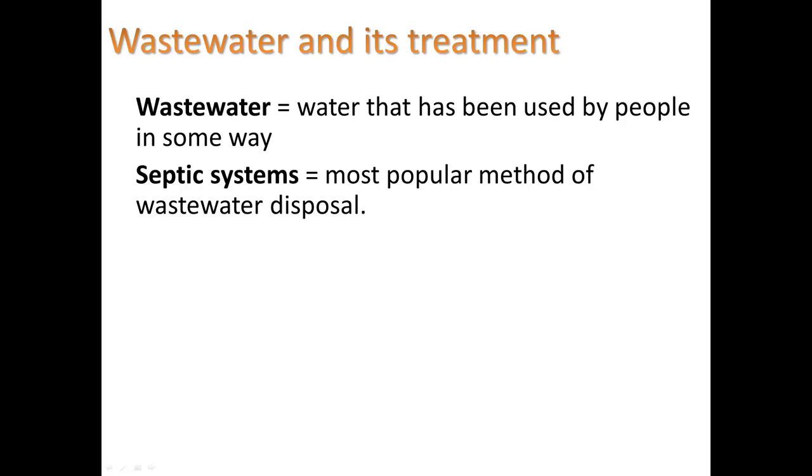Basically, the water from my drains goes into a large tank that's underground, not far from my home, maybe about 10 meters away. And it's large, like 5,000 gallons or so of volume. And the water, as it's sitting in there, is being basically purified by microorganisms, bacteria. And then the water from there goes into some pipes leading away from the septic tank, away from my house, into what's called the leach field.